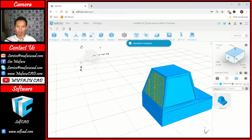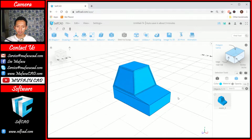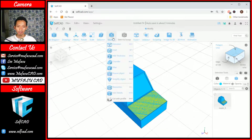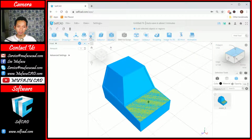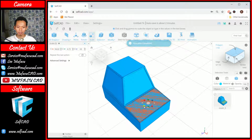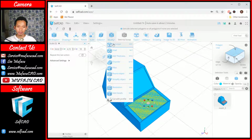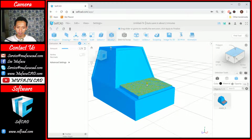Click OK to apply. Okay, the next we can select this face. I will use the insert tool, and then I will use the scale tool. You can click confirm. You can scale in the blue axis in here, and we scale again into this point. Now we can use extrusion to extrude this face. Okay, I will move to the bottom into this point.